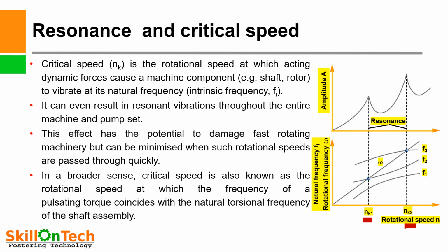So when these two frequencies match, then there will be resonance. So we should pass this resonance condition quickly, so that it will not be a cause of vibration in the pump. So these critical speeds shall be passed immediately while operating the pumps to minimize the vibration factor.